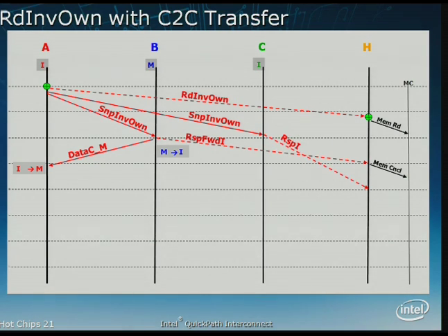Once all the snoop responses have been collected for a transaction, the complete is sent from the home agent. At that time, all the resources can be released. Also, at the time of the yellow dot, the requester can now expose to the rest of the topology whatever it did to that data. Until that completion, only people behind that caching agent can see that data.